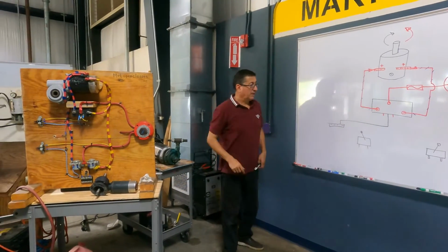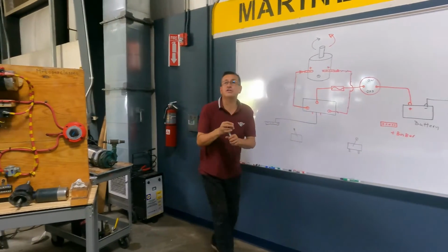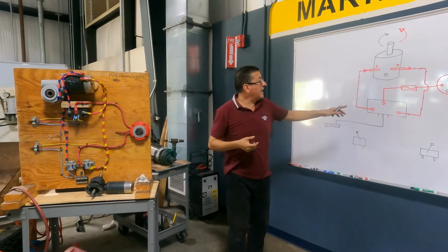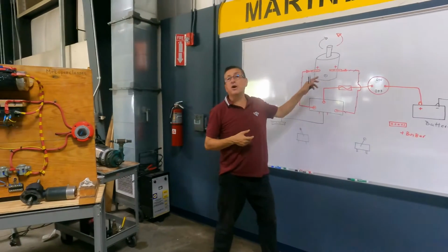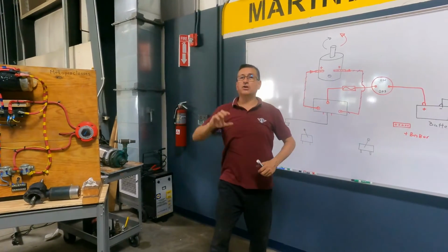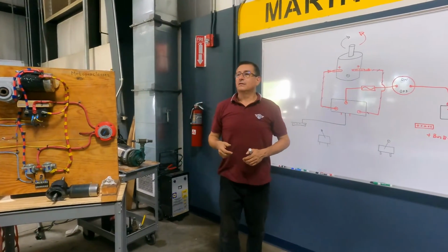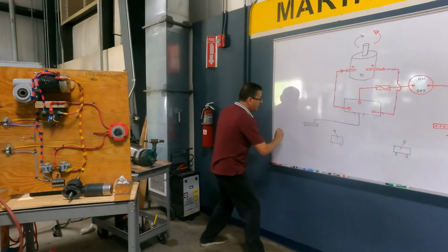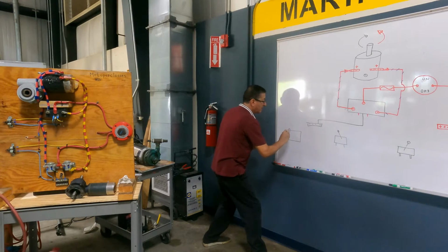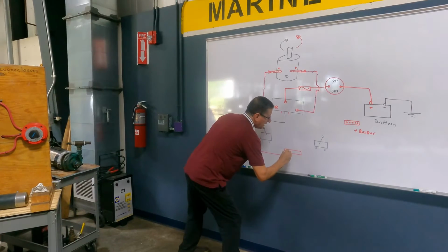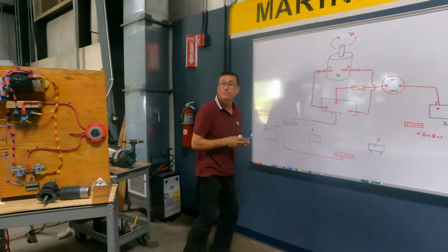Normally those switches are located where? In the flybridge, in the console. And where are located the batteries for those big motors? Over there, on the bow thruster, on the stern thruster, on the passerelle, yeah? Those are different from the house batteries. For that reason, those switches normally receive power from the house battery bank or electronics battery bank. Where is the electronics battery bank located? In the console, no? Pretty close to the console.